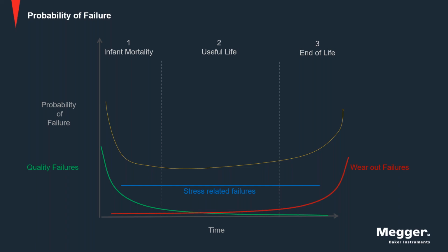So this becomes a good time to test. As you receive that motor in from the shop, or a brand new motor, go ahead and take it out and static test that motor. Make sure that its insulation system is good. There's nothing worse than having a motor fail on you. You go to your warehouse, pull out that motor that you have sitting there ready to go, put it in place, and now you've spent 2 days, 2.5 days doing the swap out, only to find that that motor was not good.